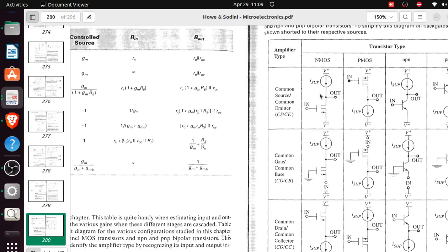So similarly for analog IC design, the current source has to be designed, and many times we use a transistor to design a current source. It's possible because from the IV characteristics of a transistor, in a region the transistor behaves as a current source, and that's the region where it's in saturation, right? So in real life, in practical design, this current source will be replaced by just a single transistor, you get.